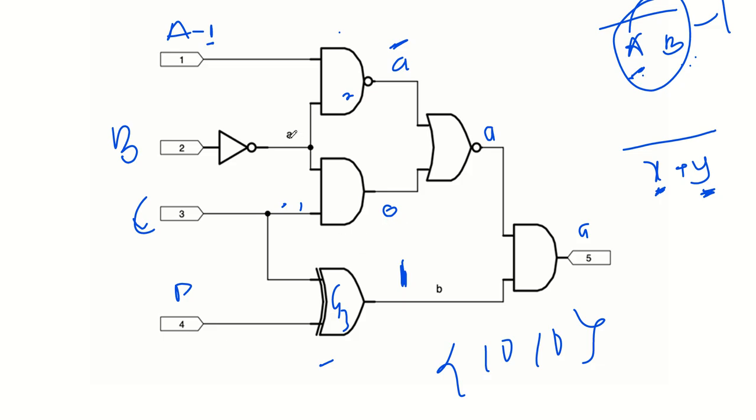At the top, it has A, which we don't know, so we don't really want to deal with it now. But I realize that if we set the down to 0, then this whole circuit will always produce 0. So why not make C 0? Realize that in the first one C was 1, but this one C is 0. So if we set C to 0, it works, right? And now realize that A was stuck at 0.